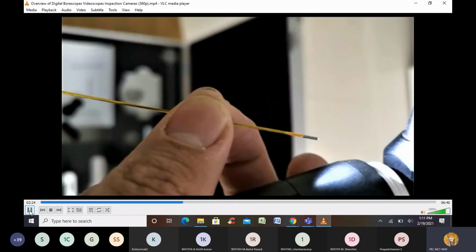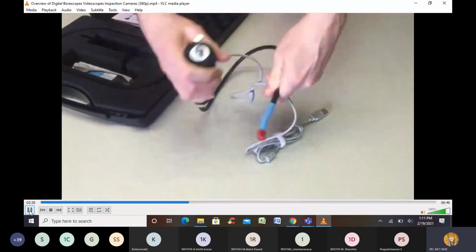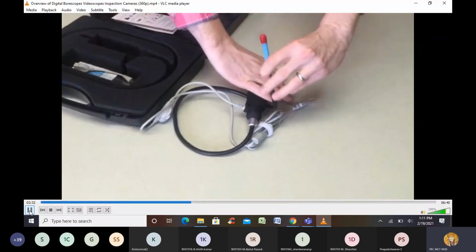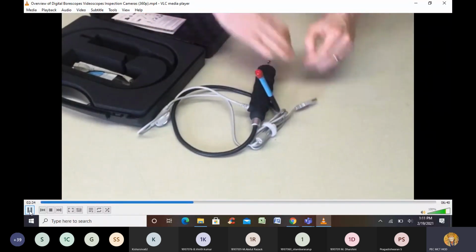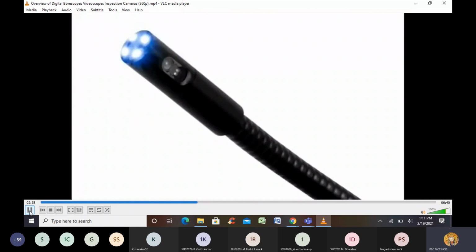Small diameter borescopes are also generally more expensive. Resolution can also be affected by the size. Larger diameter borescopes are brighter and normally have higher resolutions than the smaller ones. Smaller diameter borescopes are also generally more expensive due to the technology limitations and cost to produce quality images with very small cameras.